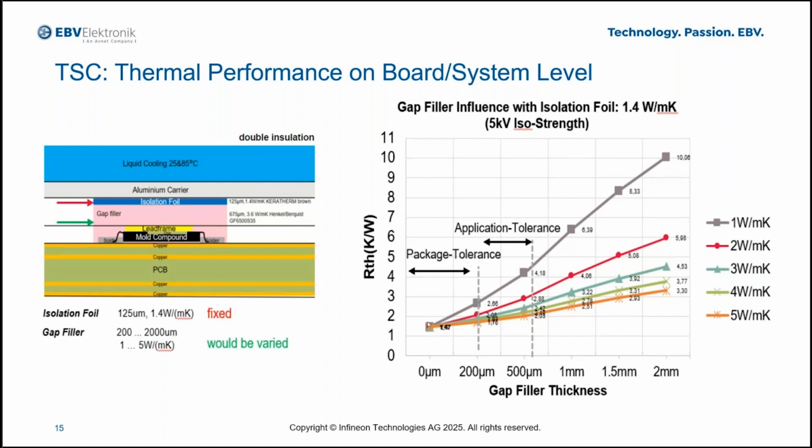in the order of magnitude of 2 Kelvin per watt, you basically reach what is comparable to a TO247 device connected to a heatsink, but with the advantages of SMD.